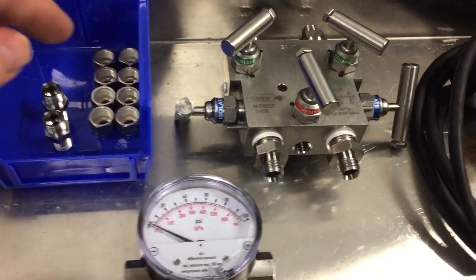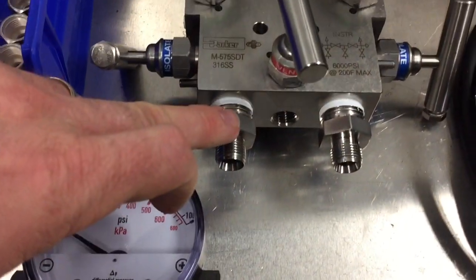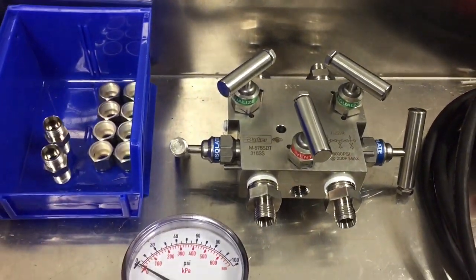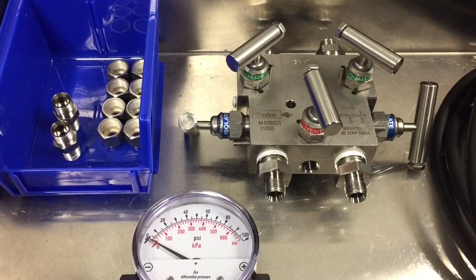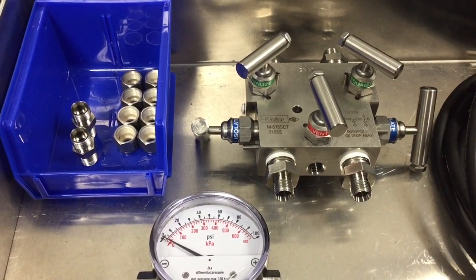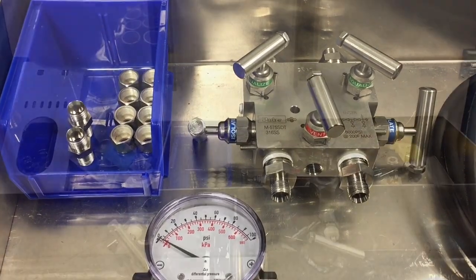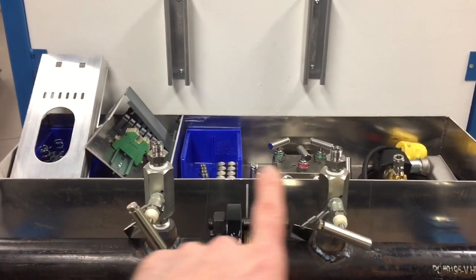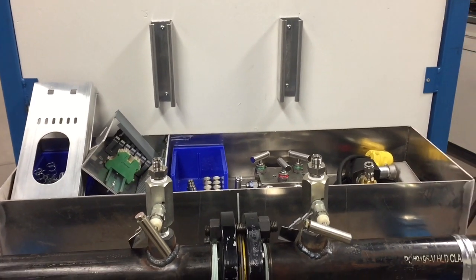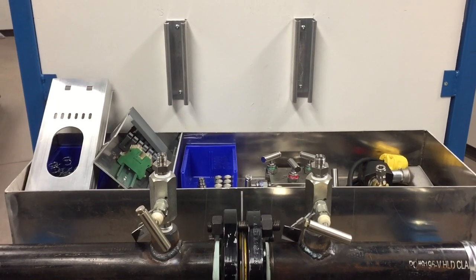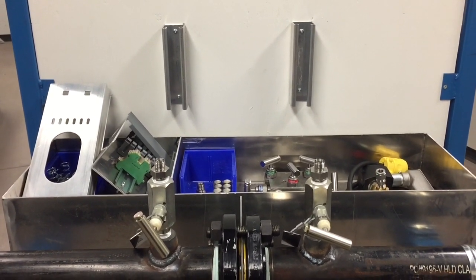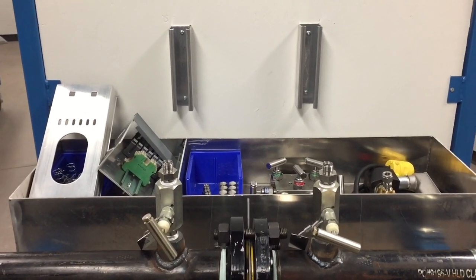And then eight nuts and the 5-valve manifold, with these fittings left in them. All the fittings can be left in the 5-valve manifold. And all of your scrap tubing left over from cutting the nuts off will be thrown in the steel bin and recycled. One other thing I wanted to point out is the measurements between these two needle valves. The center-to-center measurements that we made earlier in the lab may be different on every trainer, so you will have to make those measurements on your own for your tubing bends to be correct. So make sure you make those measurements for the lab yourself.